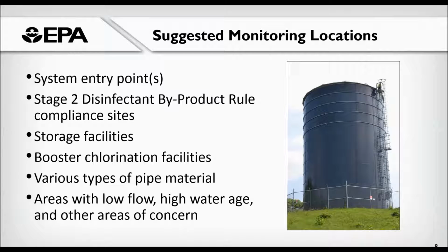If a system has booster chlorination facilities, we strongly encourage that samples are collected both upstream and downstream of those. That allows the system to understand what levels of chlorine they have entering and leaving the booster facility.